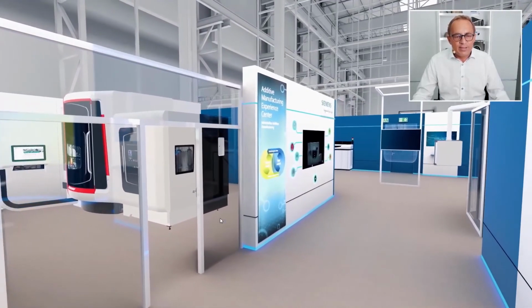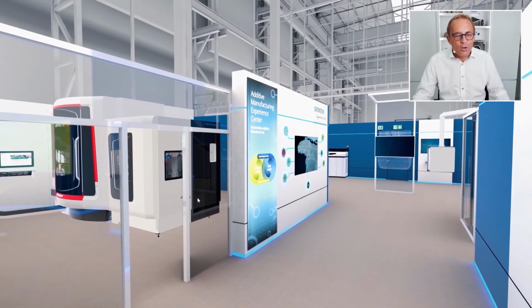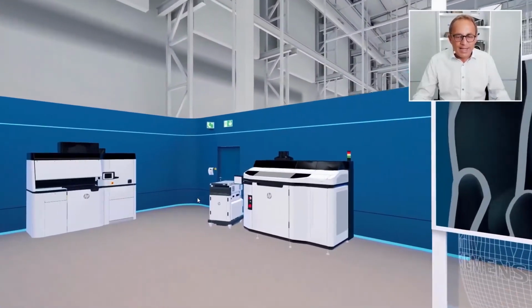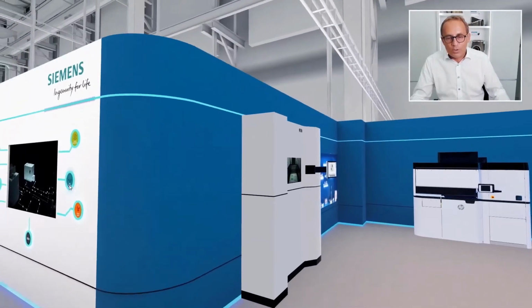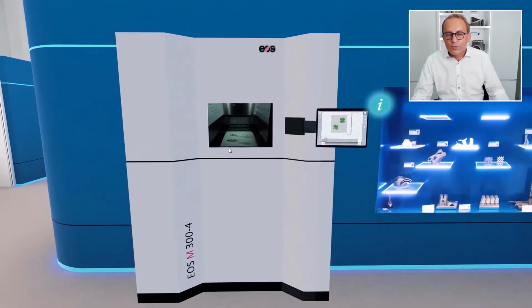Here on the left side, you see the DMG Mori LaserTech 65 3D machine, where we can do directed energy deposition, printing, turning and milling, all completely in one machine. If we go a little bit ahead on our shop floor, you see on the left side an HP machine representing the jetting technology, the newest HP industrial machine, the 5200. And we can also see an EOS machine, an EOS M300. This is a powder bed fusion machine where parts can be printed with a metal powder bed.